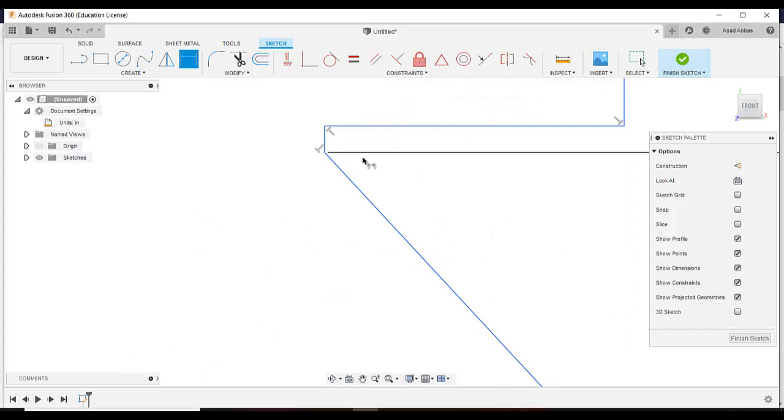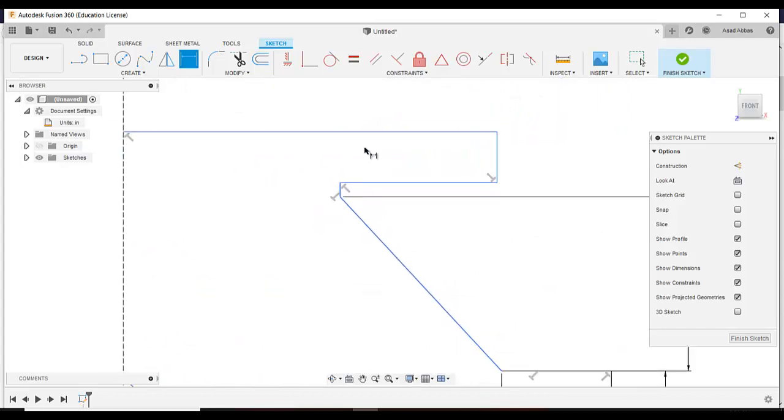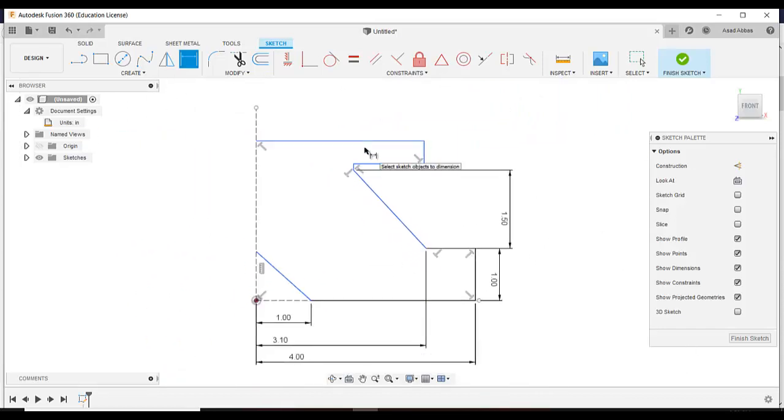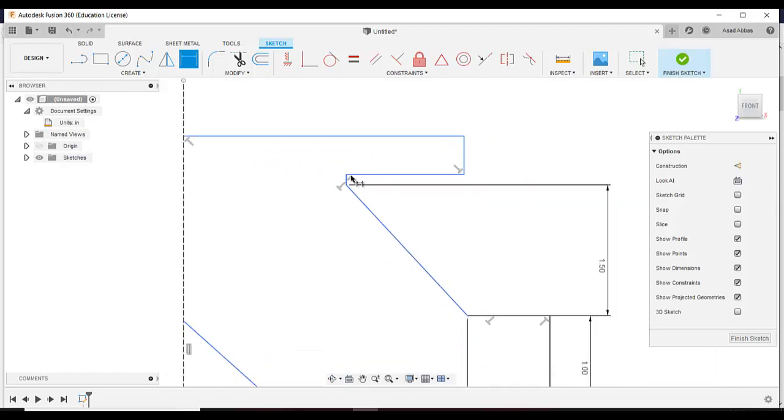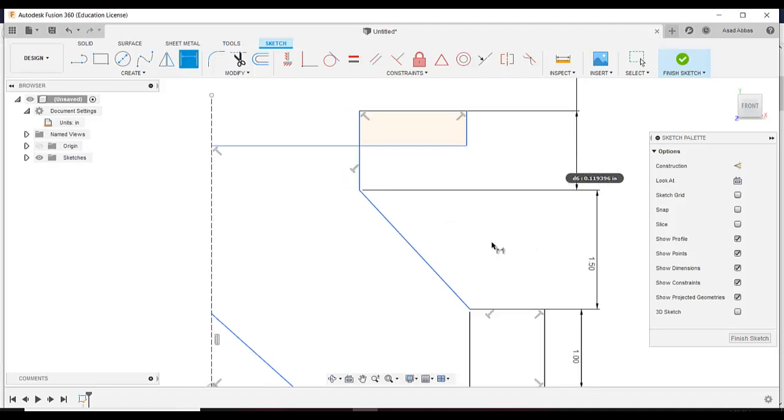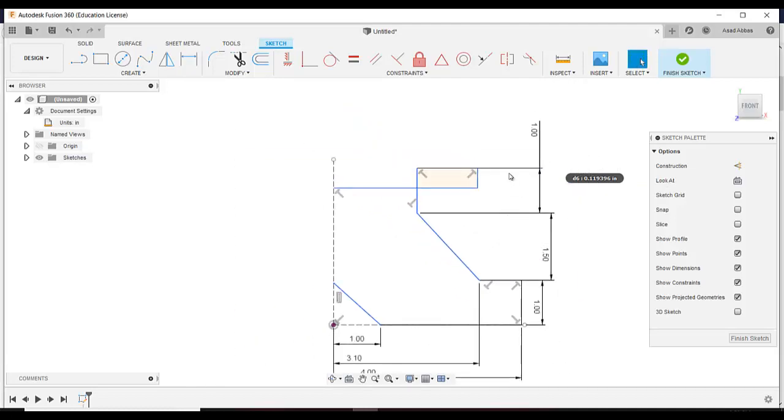And then you can zoom in or zoom out to make a feasible location of this sketch in front of you, which will be easy for you to select the dimension. So the dimension for this line is given as 1. Okay, it moved this line above this line, but we just needed to make it like that.